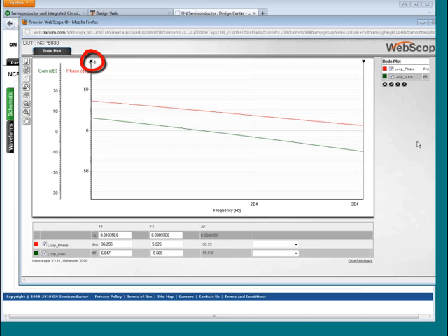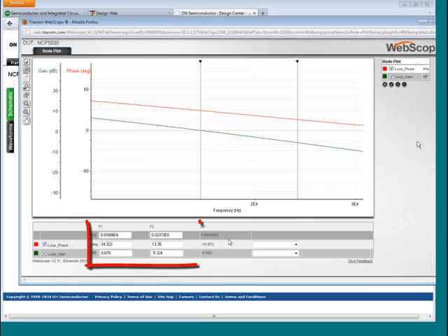If you see these two little triangles up here in the corner, you can drag these and actually set those at a couple of different points here. And as you see here in these little points right here, you can see that it's following the frequency. So I can see that my crossover here from my gain is right at about 7.6 kilohertz, or excuse me, my crossover is about at, it's the F2, it's the F1, which is this marker, and it is at about 16 kilohertz.